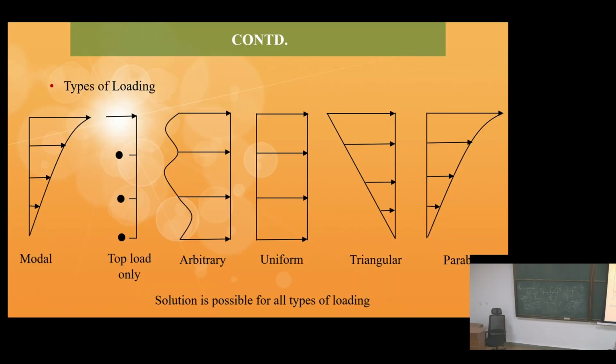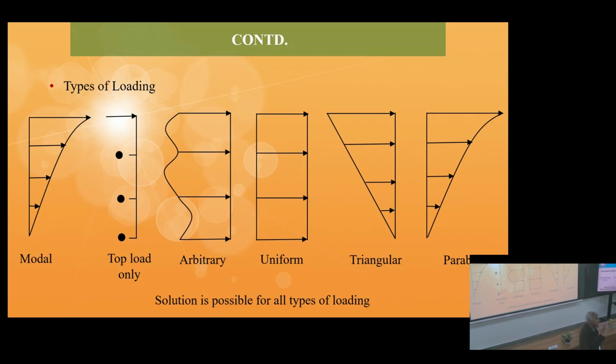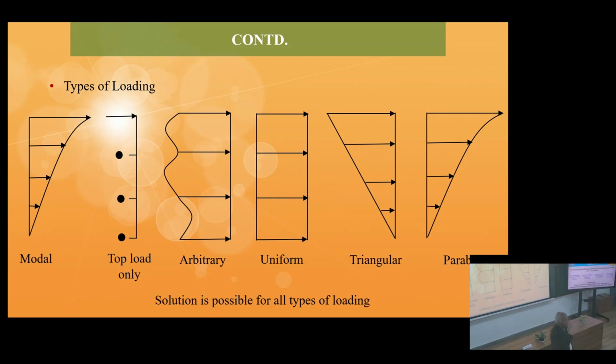So now let's say for this building there is a fundamental frequency, and correspondingly there is a shape which is called the fundamental mode shape, and in this fundamental mode shape it is vibrating. Okay.